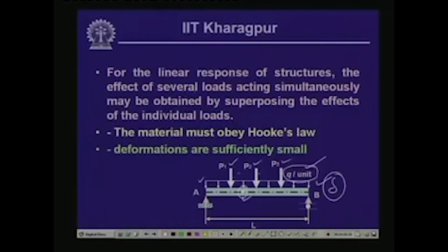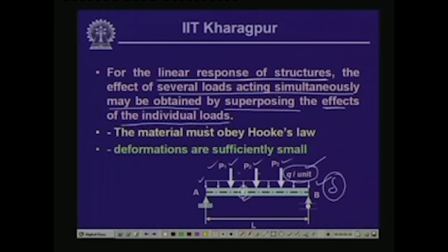And this is what method of superposition says, that for the linear response of the structures, and this is quite important, when the response of the structures is linear, it means that the deflection which we compute is a linear function of the load, and then the effect of several loads acting simultaneously may be obtained by superposing the effects of the individual loads.